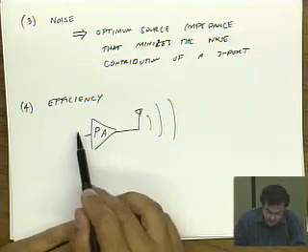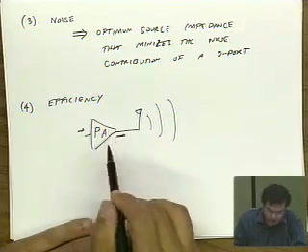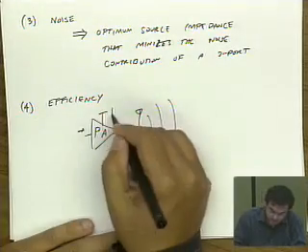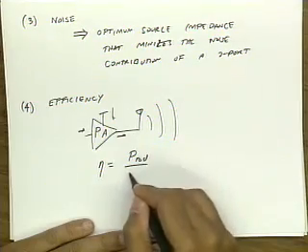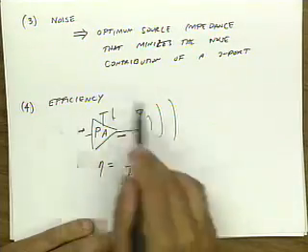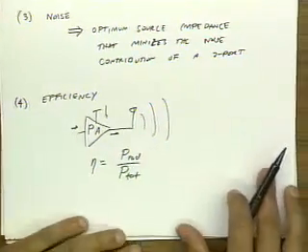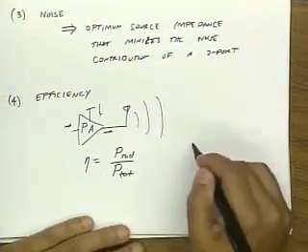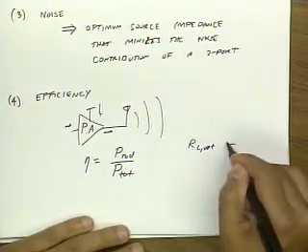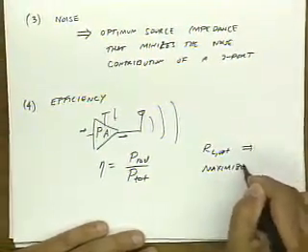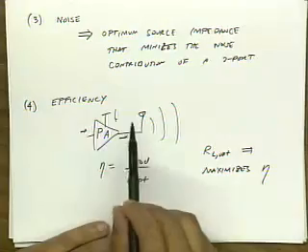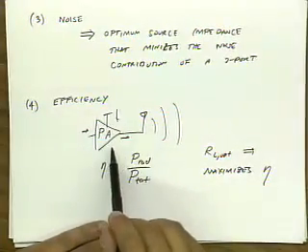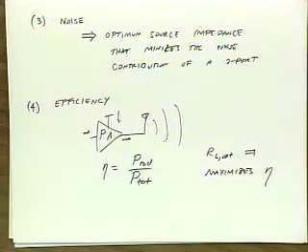So let's say the power gain is how much input power you put in versus output power, if you can improve the efficiency. Now the efficiency is the power, let's say, that we radiate versus the total power consumption in the system. And what we'll find in this course is, again, there is an RL optimum that maximizes efficiency. And so when you design power amplifiers, we won't be concerned with power gain, we'll be concerned with efficiency. So these are some 4 important reasons why we should care about impedance matching. Okay.